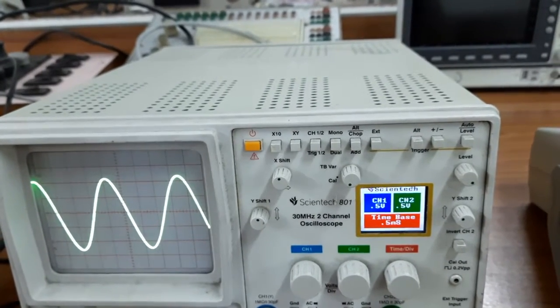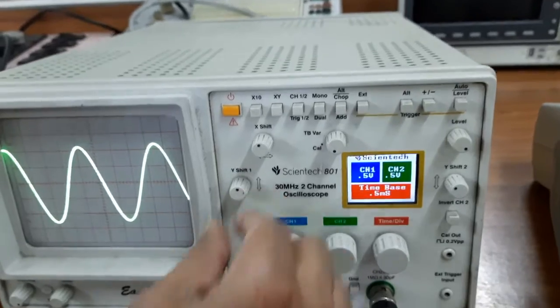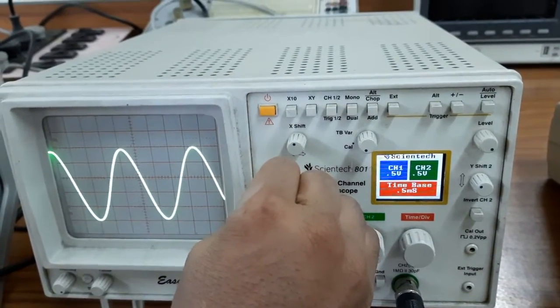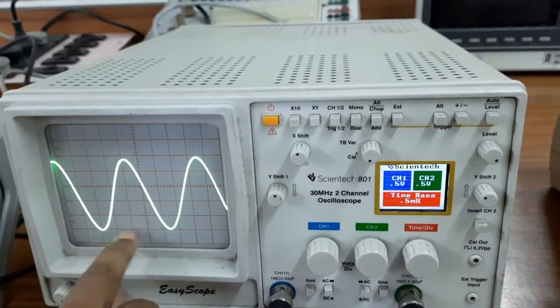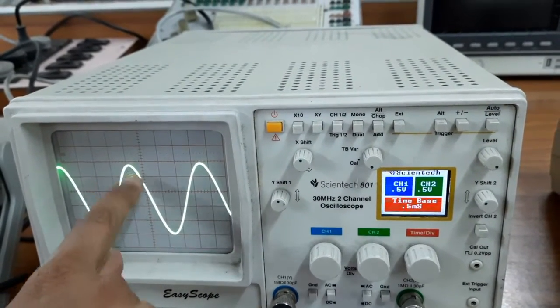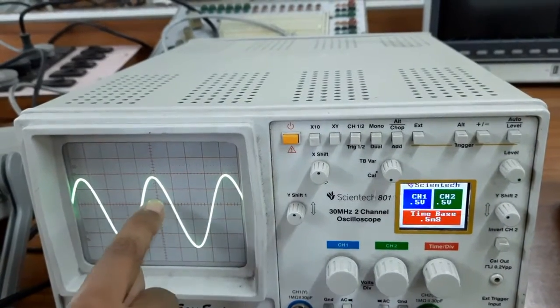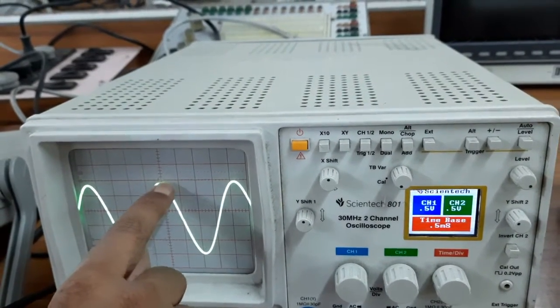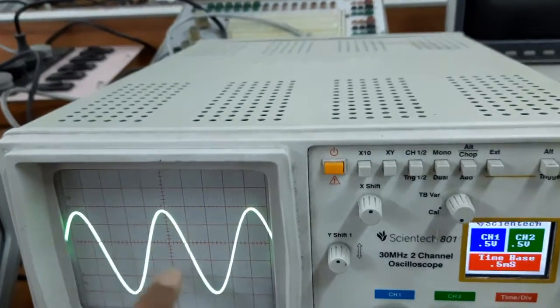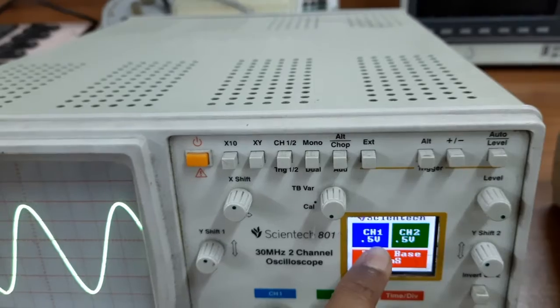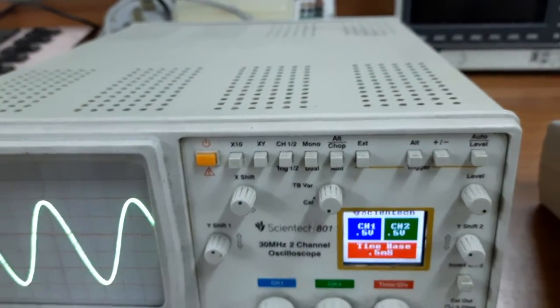Now our signal is connected to channel 1. The vertical movement of the signal we can shift by this one. So now we are setting our lower level to one of the axes, and we will measure the total length. You just follow. How much is it? It is 1, 2, 3, 4, 4.8 divisions. 4.8 is the division, and the scale for channel 1 is 0.5. So what is the voltage? I am telling you.